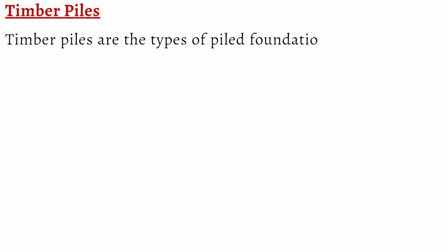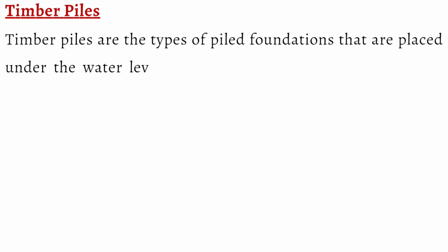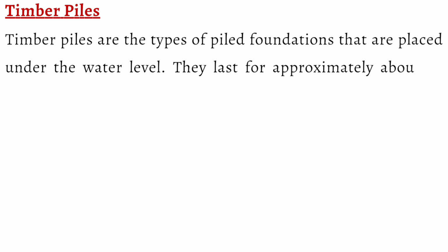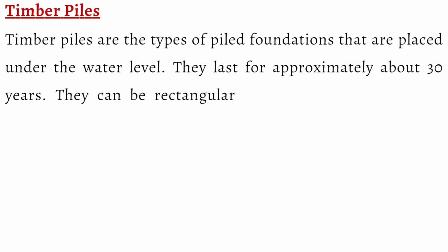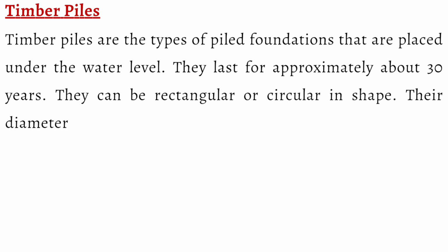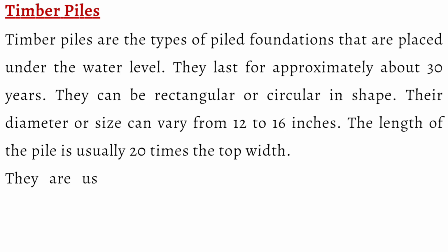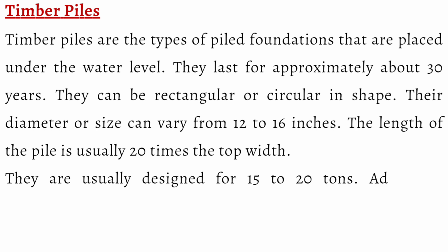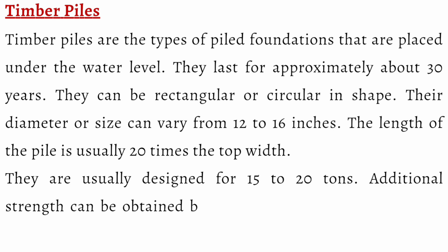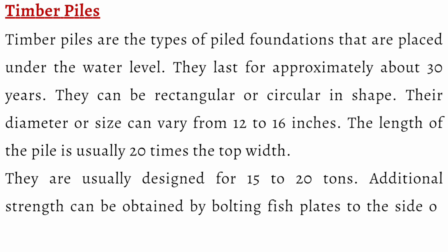Piles that cause the soil to be displaced vertically and radially as they are driven into the ground are known as displacement piles. In the case of replacement piles, the ground is bored and the soil is removed, and then the resulting hole is either filled with concrete or a precast concrete pile is inserted. On the basis of materials of pile foundation, construction and their installation process, load-bearing piles can be classified as follows: